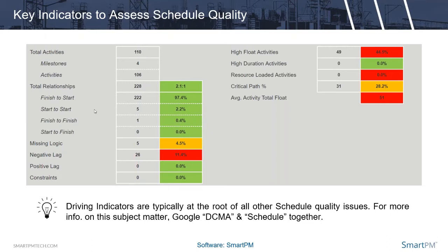I will not finish activity 2 until a couple days after activity 1 is complete. A good example of that would be drywall and paint. I will not start my paint until 4 days after I start my drywall, which may not be completely done on the floor, but to get efficiencies, I'm going to start it. And I therefore will not finish the paint until the wall's up, and probably a few days after that. So that's tracking those types of relationships.